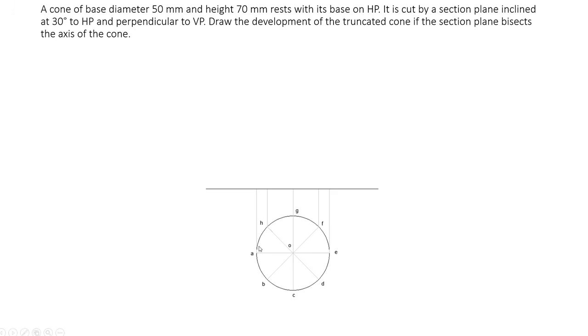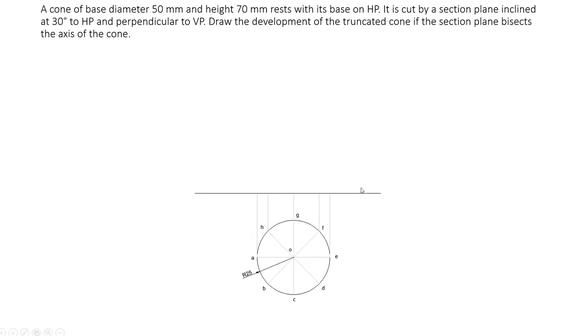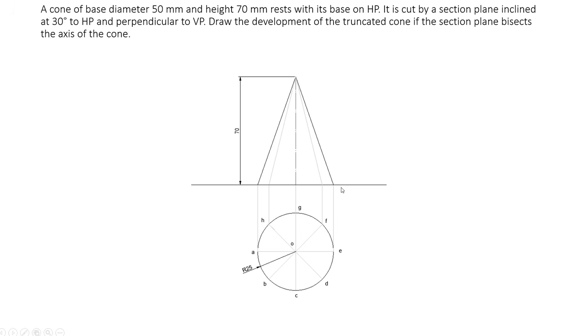Now after drawing that circle and dividing that circle, project all these points to the reference line. Mark the radius as 25 mm. Now height of the object is 70 mm. So from here, the centroid, mark height of the object 70 mm using a chain line because it's a centroid axis. So from here you draw 70 mm upwards using a chain line. Do the dimension 70 mm.